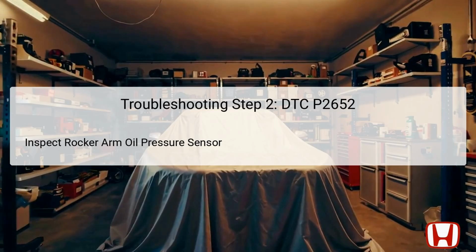To inspect this component, the rocker arm oil pressure sensor must be disconnected from its wiring harness. Following this, check for any visible damage to the sensor or its wires, including frays or corrosion, which could lead to faulty readings. It is important to note that since there is no direct method to test the pressure sensor, you will be troubleshooting its related components instead.